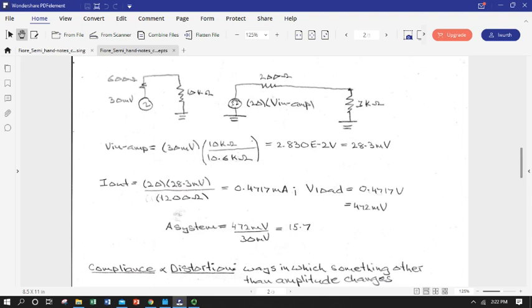Okay, we're going to lose a little more because we're going to flow some current through this output circuit, because we've only got a 1 kilo ohm load. So there's going to be a fair bit of current flowing through this. So we're going to have the opportunity to drop some voltage over this 200 ohm internal resistor, regrettably. So how much current do we have flowing? Well, we gotta see what our actual voltage source peak is.